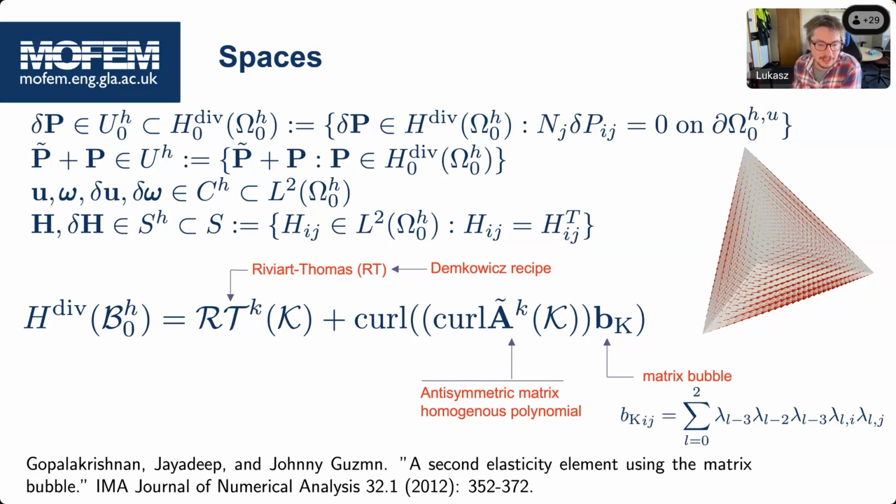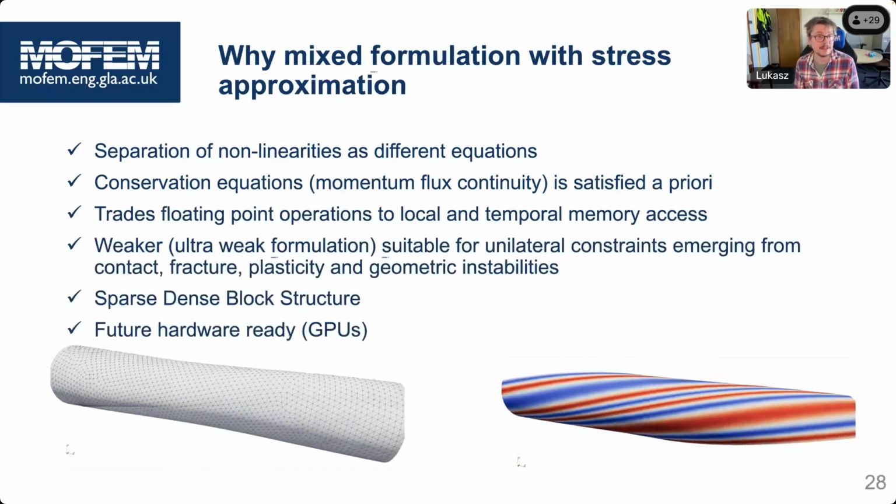What I want to say is that we limit our application only to tetrahedra because this is what the industry needs. Making meshes for hexahedral meshes is very difficult. Delaunay triangulation is one of the most robust algorithms, so we want our method to work with tetrahedrons. And as you know, that is not so easy when you're dealing with large deformation and nearly incompressible materials. But thanks to that formulation, everything works well.